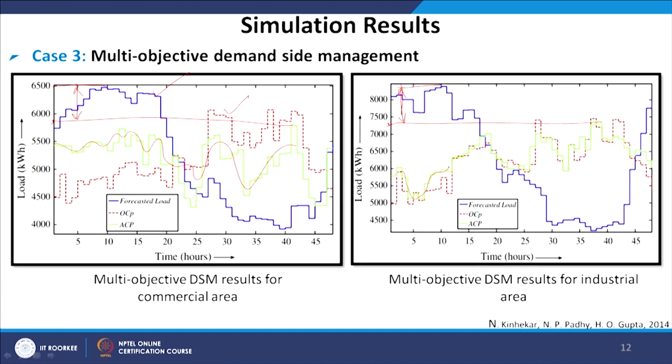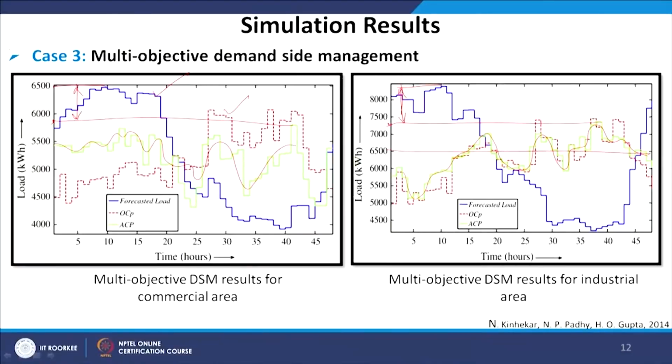The simulated load curve that has been obtained cannot be made flat, number one, because the devices have to keep on varying, and you cannot force some of the devices to change as per your requirement. If you could control all the devices, which is not possible, mathematically the characteristic could have been flat. But in a practical scenario, a few devices cannot be shifted, and those that can be shifted may be shifted maximum for 4 to 6 hours.